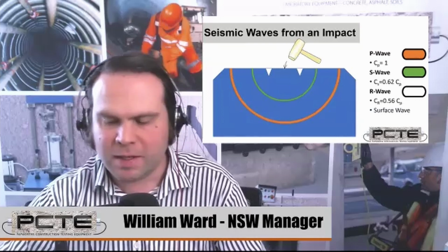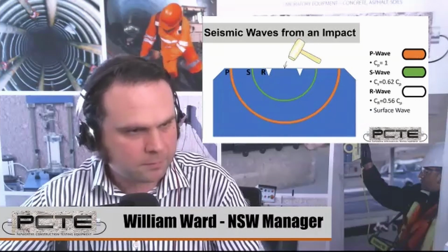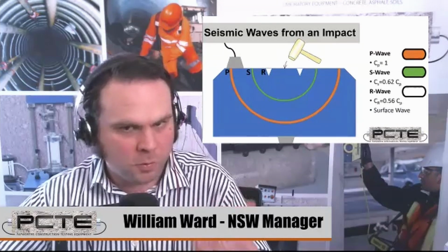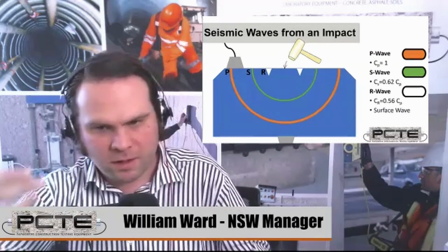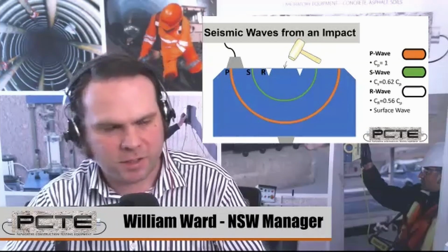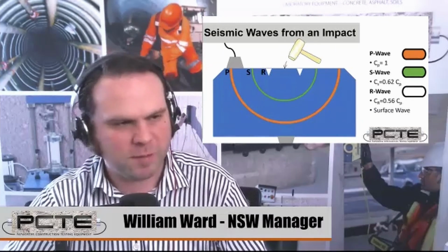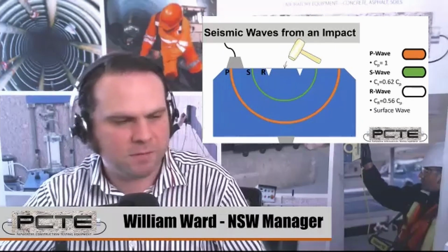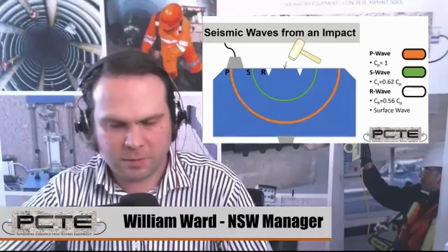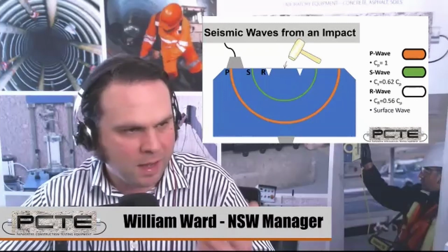It means that when we are doing a technique such as ultrasonic pulse velocity, we would want to put sensors. It's appropriate to use compression waves because it's the first arriving energy. So most ultrasonic pulse velocity measurements will be compression wave measurements because it's the easiest to measure. It's the first arriving energy from a transducer which puts energy into the structure.